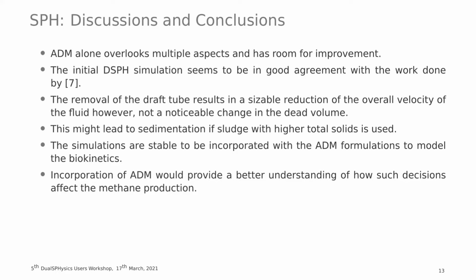The second is that the initial simulations that we saw with the draft tube were in good comparison with the ones done by Masood et al. And the third is that the removal of the draft tube results in a substantial reduction of the overall velocity of the fluid, but not so much of the dead volume.